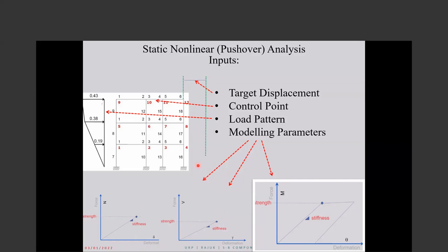The third one is that as you push, these force control actions come, but don't pass the limits. But the deformation control action, like here bending moment versus bending deformation, if this passes the yielding point, because it's a ductile behavior, it has some level of ductility.